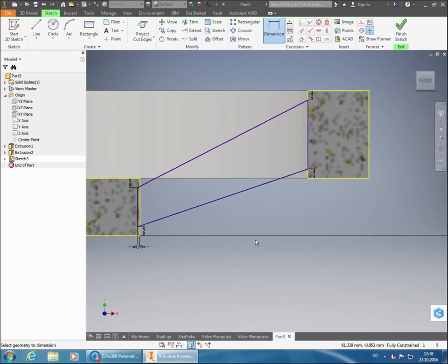But as you can see from the drawing, we're going to also have a slight knob on the end here where the spoke is. So we're going to put in a rectangle here also. So we're going to place a rectangle. We're not going to attach it to anything right now. We're just going to set it up here. Because with this rectangle, we're going to have the same problem as we had over here, because now our ring is curving away from our extrusion, so we're going to have it go into the extrusion there also.